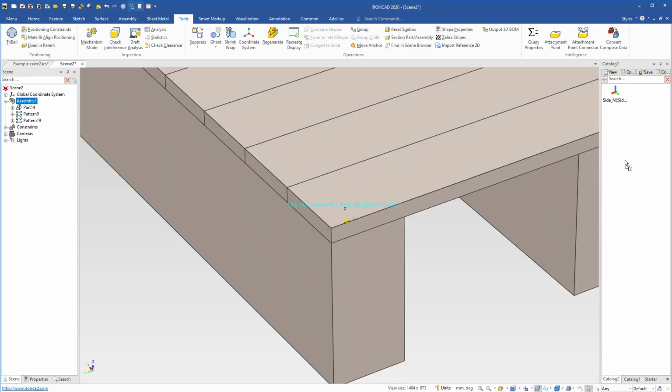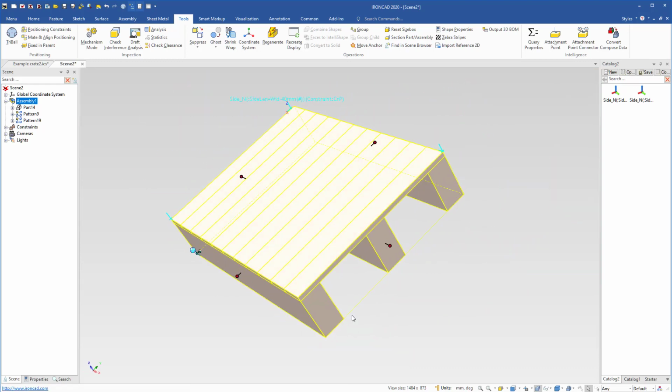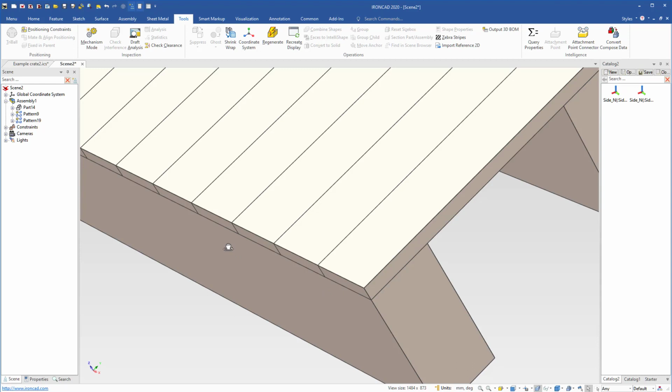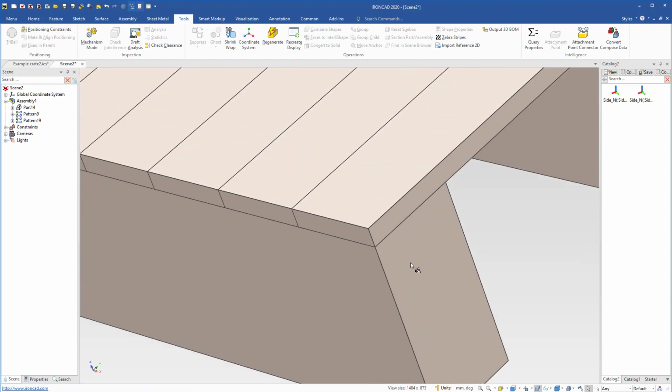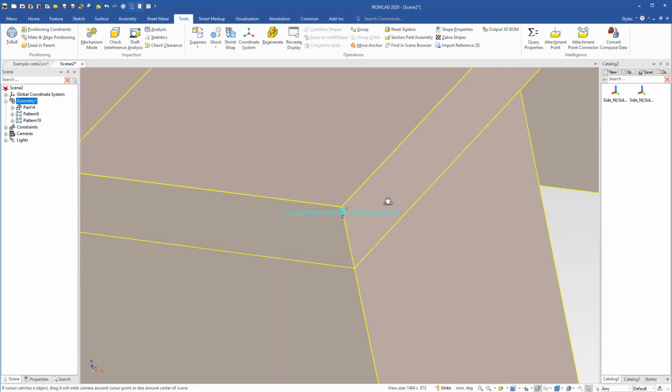So we can see this one's a little bit different, but it's going to do the same exact type of behavior. So again, we'll drop that into the catalog, and we're going to move it over to the other side. Again, in this case, this board's going to move out, so we're going to drop it onto this board, so it needs to know to shift and adjust with this guy, or drop it on the edge. You could have dropped it on the edge on the other one as well, but we're just going to drop it on this edge. Again, select it, use our tri-ball, move it up to our point here, and obviously kind of take a look to see how we're situated.